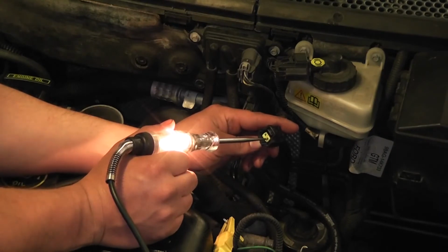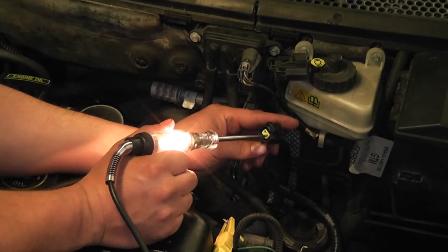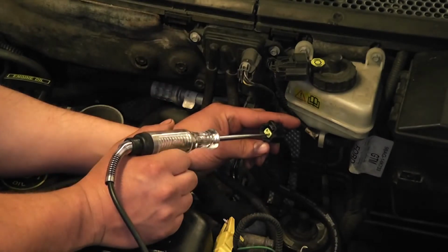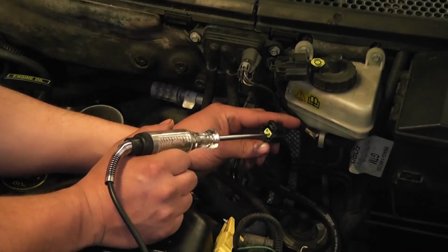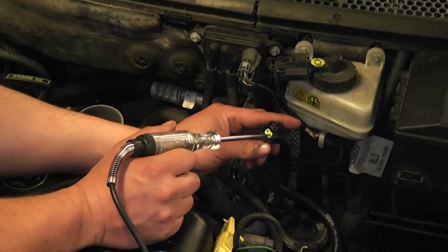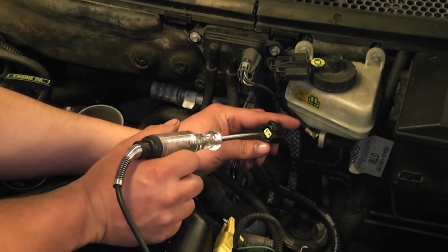What I was going to tell you is if this test does not function, what we might have to do is clear the trouble codes. With a hard fault in memory, the computer may disable that output. But you can see right now it is functioning. Turn it off and turn it on. And what that's going to tell us right there is that that computer driver is functional and that control circuit between the solenoid and the computer is fine, and we can go ahead and safely and confidently put a solenoid in this car.